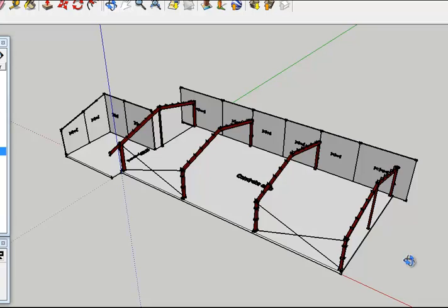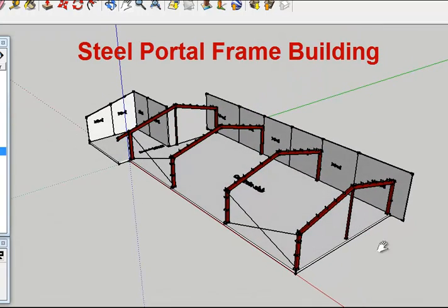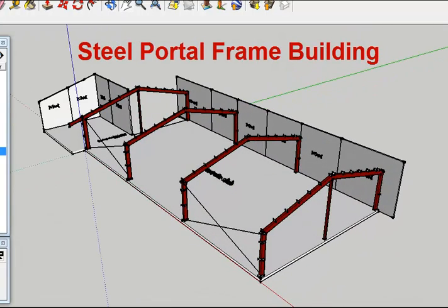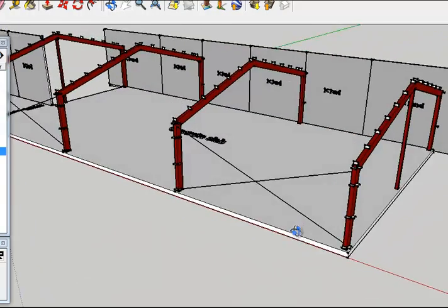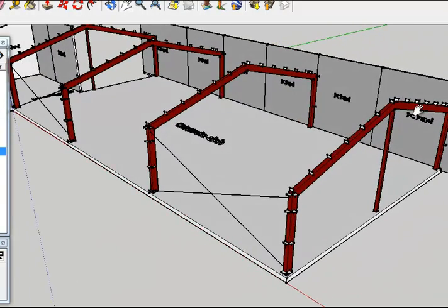In the case of steel portal frame construction, it's quite different. You can see, for starters, that we have a low vertical level but expansive footprint. And so this is a very common type of construction here. We've got a steel portal frame constructed of, depending on the size, it could be one unit fabricated on site or delivered to site, but quite often, depending on the size or the span, it's going to be made up of more pieces.